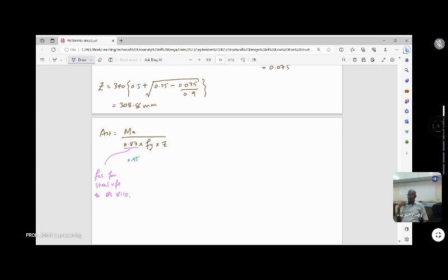So with that, I want to ask a question which you can answer yourselves. You don't need to answer in this class. Would you rather work with 0.87 or 0.95? I choose to work with 0.87 because we have not yet refined our quality control in manufacturing of almost everything to say now we can assume we achieve 95% of the characteristic yield strength of steel.